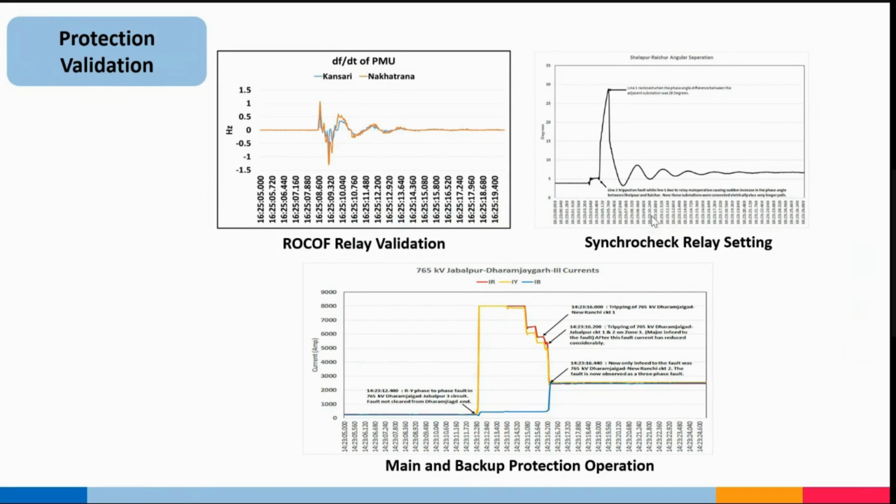So you can see that the protection is operating, let us say there is a fault. In Indian standard, the minimum fault clearance time is 100 millisecond at HV level. If you go to the 220 kV level and below, it is 160 millisecond. So 100 to 160 millisecond is the response that you need to clear the fault through your main protection system itself. Roughly, if you divide it by 25, for let us say 160, you can have 4 to 5 samples of data for that particular fault.